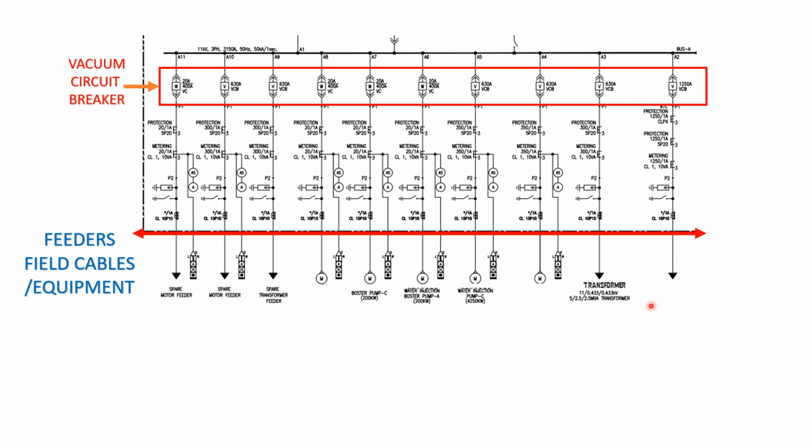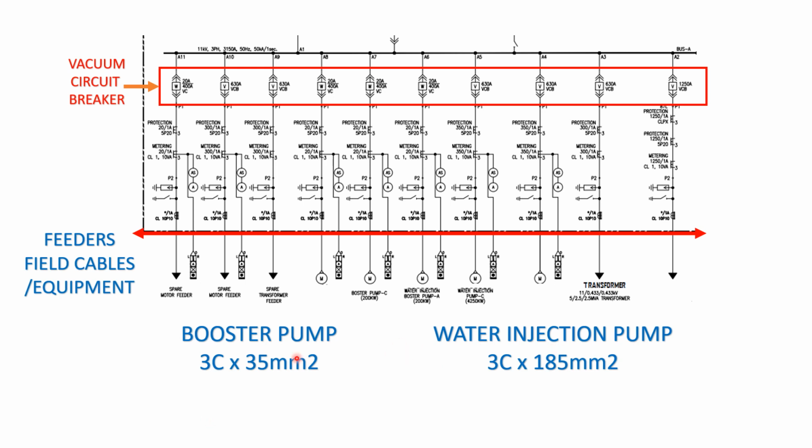Motors, what kind of load, transformer, that is our field side. There are motors, how many kilowatts depends on the requirements. And then how much the size of the cables is based on the load requirements. So we identify the cable size. We have different sizes of cables based on the load requirements. That's how we identify, and the calculations come from the engineering.